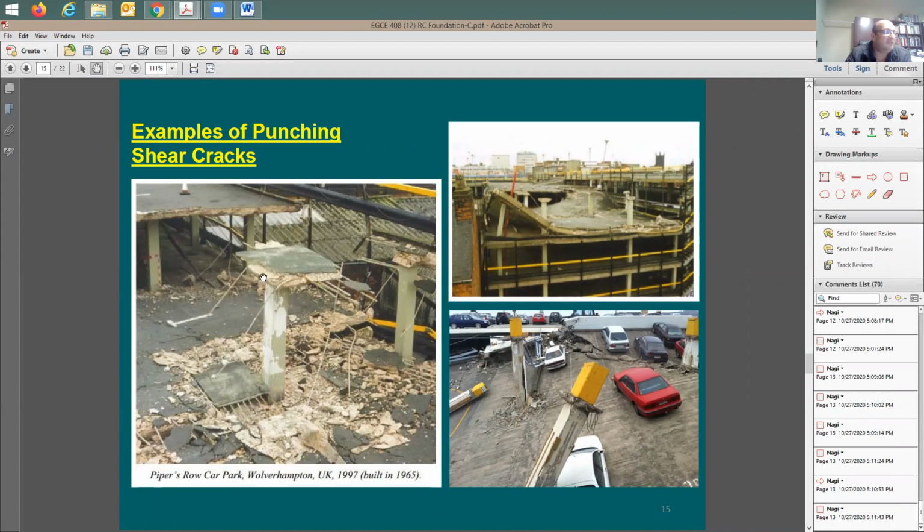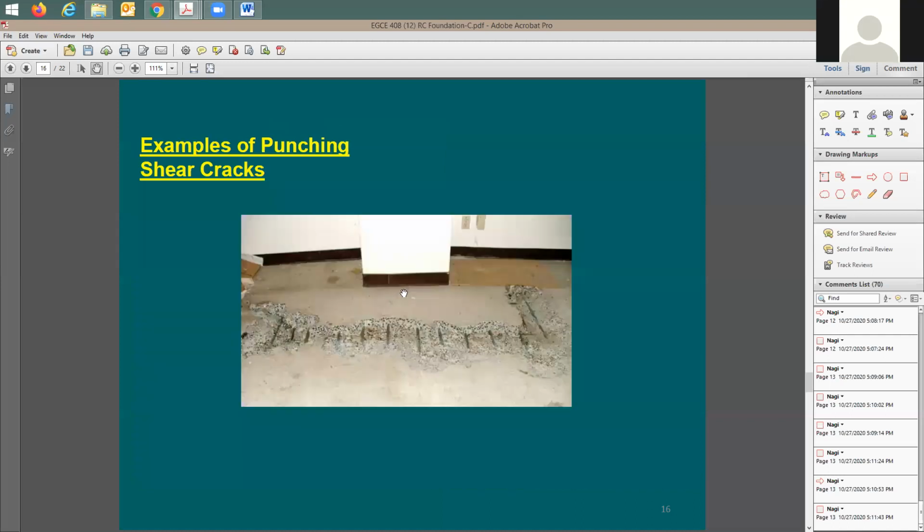We go below the concrete slab, and then we start to add some mechanical connectors, channels, and stuff. On the top also you can add layers of FRP. So there's a way to fix it. You do it from the top and also from the bottom. But the one from the bottom is really important. You really need to do something from the bottom, not just FRP. I've done a project like this.